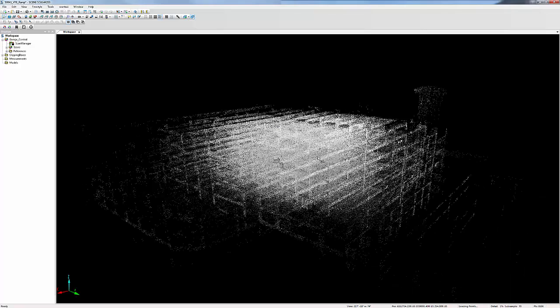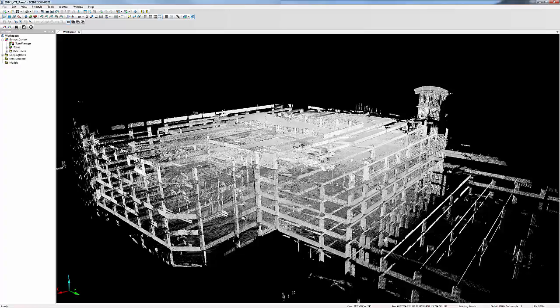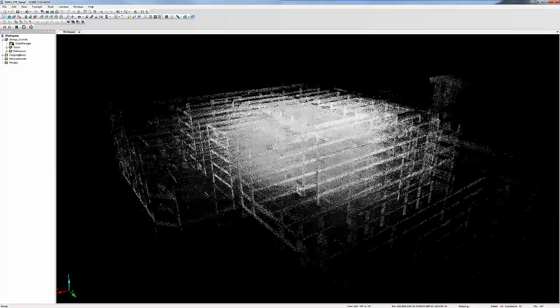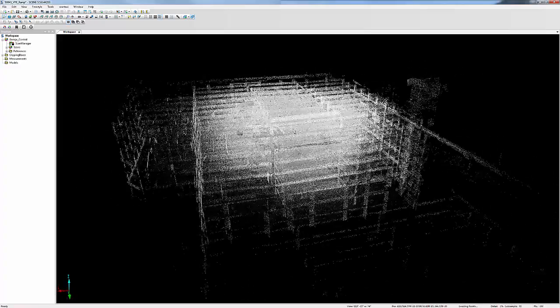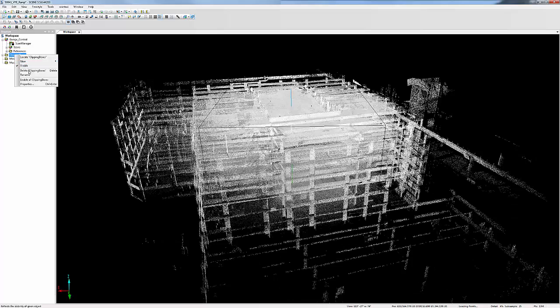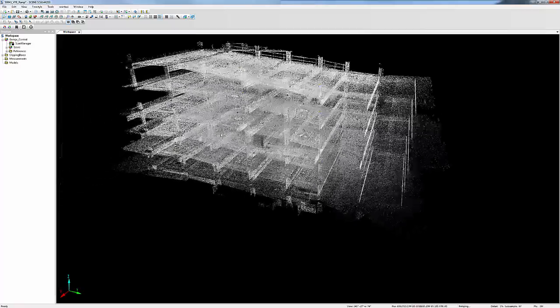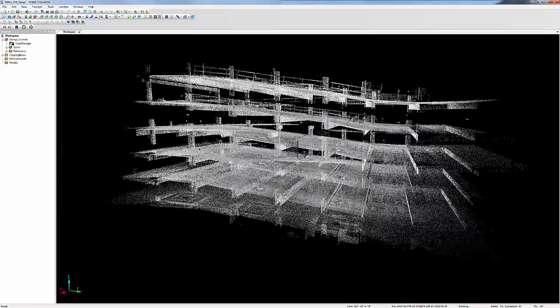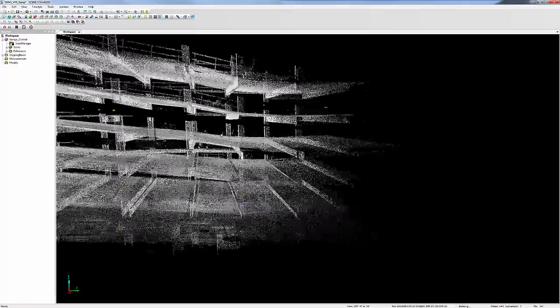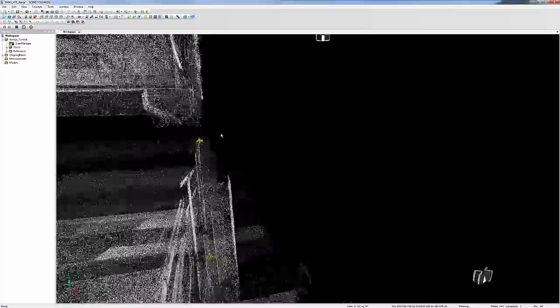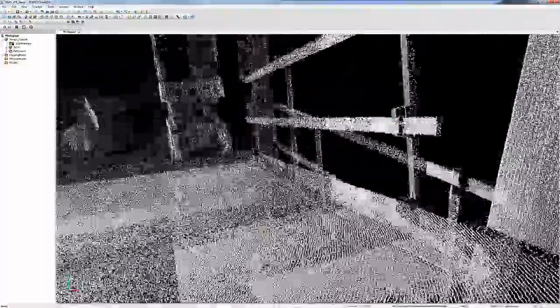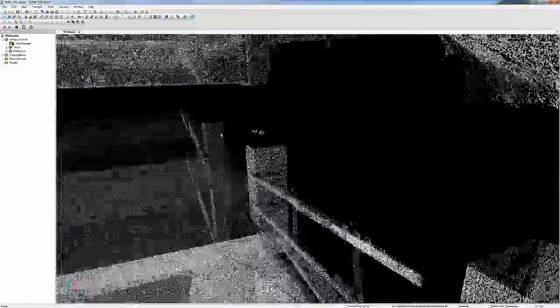For this certain parking structure, we wanted to run multiple sets of analysis on the parking ramp. So what we did is we went ahead and scanned. We set up control and targets on every other column on each floor within the ramps. Notice how our targets are on our column lines on each floor.